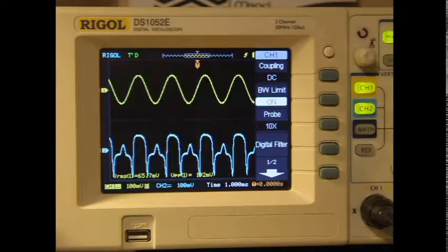Not that most of you care or even would understand, but the classic Octave Fuzz pedal used by Hendrix et al., that is sort of the archetype of this type of effect, used a transformer to basically get copies of the signal that are out of phase with each other, which is sort of the first step to making a full wave rectifier, with the diodes then being the second step.